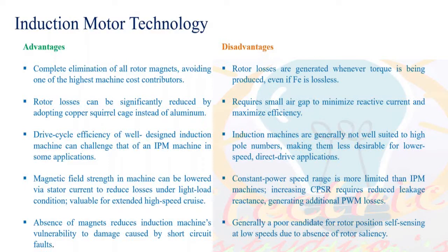So because of that, when you have an induction motor, you don't have the freedom to operate in a wide range. That is one problem. That is why right now Tesla is using another motor. What is the other motor they are using in addition to the induction motor? What is the other motor that Tesla uses in the Model S and Model 3 in some of their models? Any guess? Actually, the answer is permanent magnet assisted synchronous reluctance motor. That is the full name we have to call.